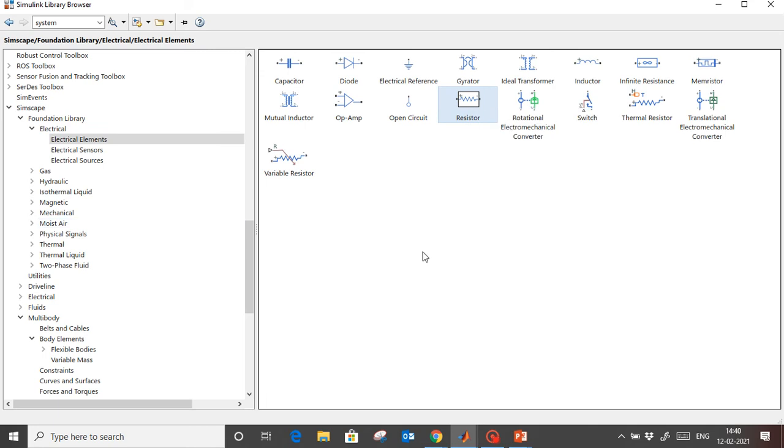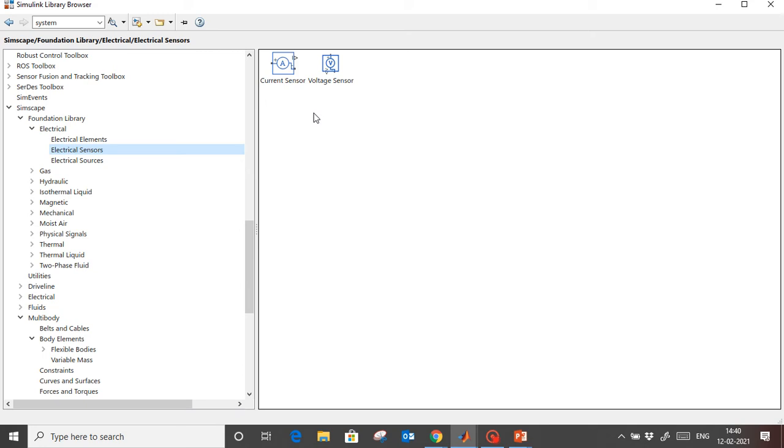Okay, we have some components available now. Next, to sense from there, for the sensor, what are we going to sense, a current sensor or a voltage sensor? Let's say we are going to measure voltage. So the voltage sensor will be added in parallel. If I have to measure the current, then we will use a current sensor, and it will be added in series, right?